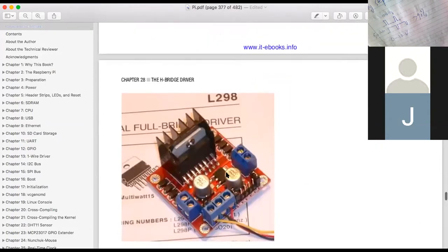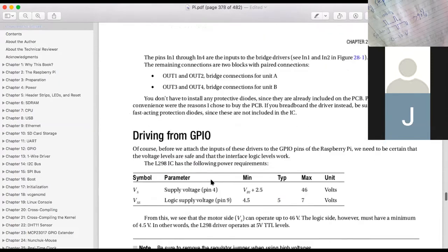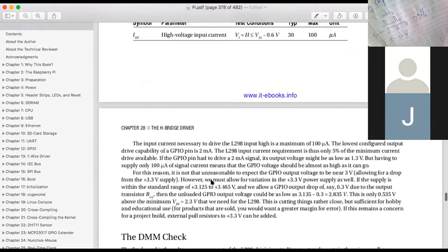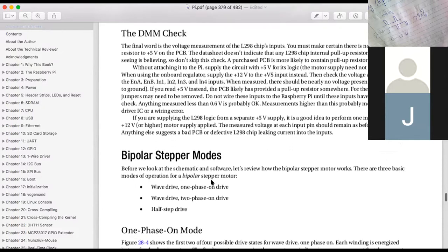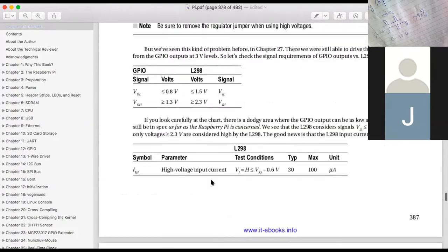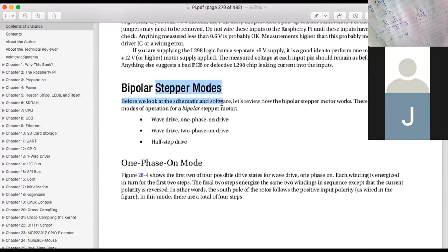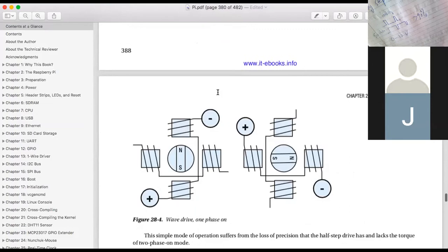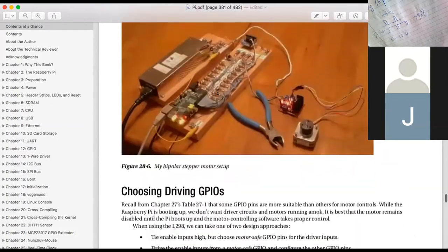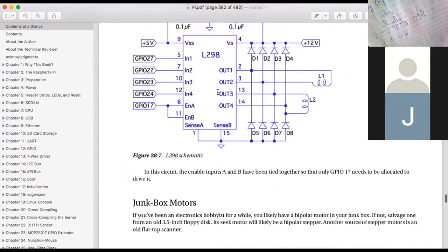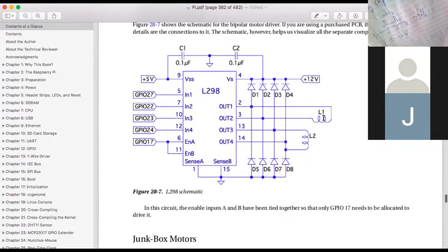So that is an H drive, and we can program it with a computer, and we can drive a DC motor. Then how about another type of stepper motor called a bipolar? The bipolar stepper motor has only 4 wires like this. This is a bipolar. So the bipolar stepper motor has only 2 coils, and these 2 coils have 4 connections. So that's called a bipolar.